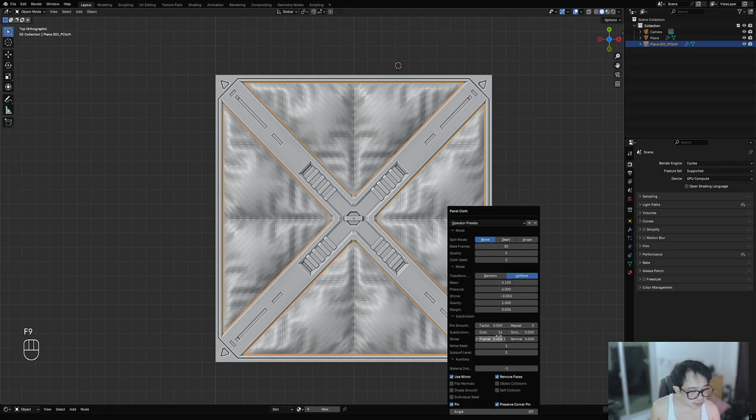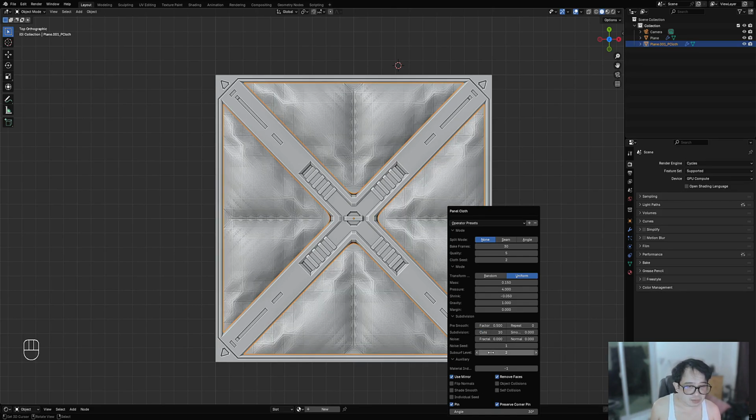We're going to try getting rid of the symmetry, but first we need to lower the subdivision because the process will involve using the script on the applied geometry. So it means that the faces from the mirrored side of the geometry will now be real, and therefore add to the processing speed.